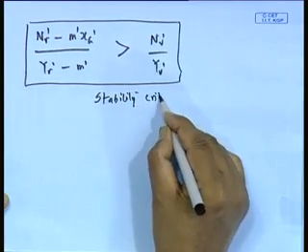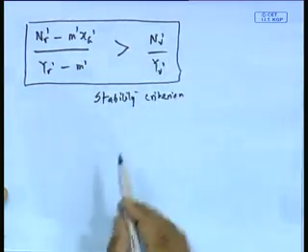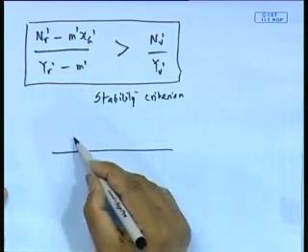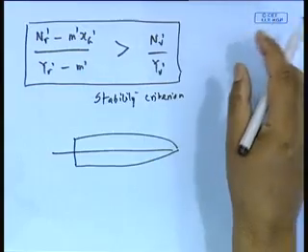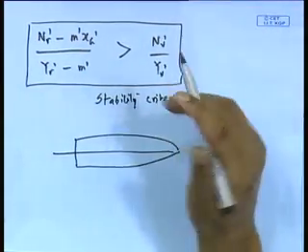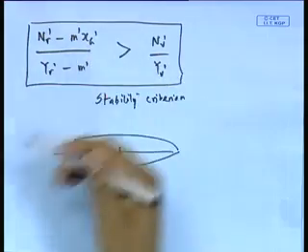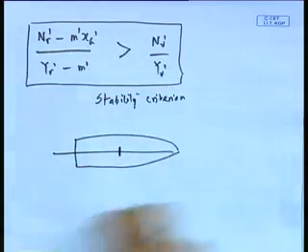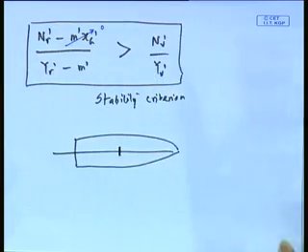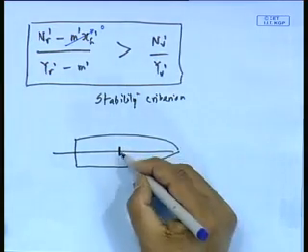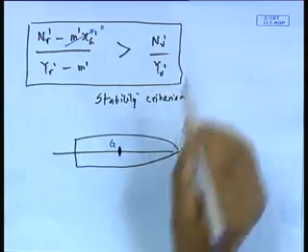Let us put some physics into it. Let us look at this term. Take this shape. What we will do is put O at CG, so that I do not have this term, because it is up to us, we can always put that. So, if I put xg as 0, it means this origin is at G. Now, let us look at this Yv by Nv.